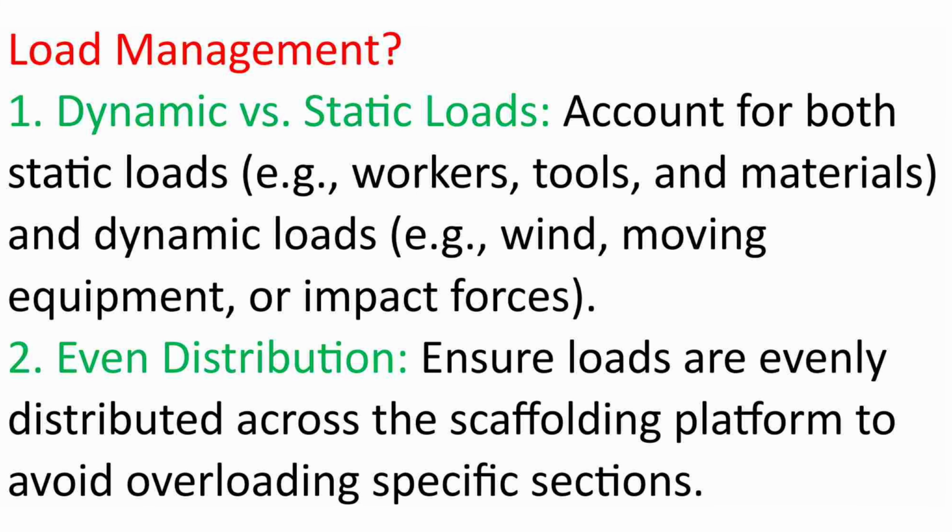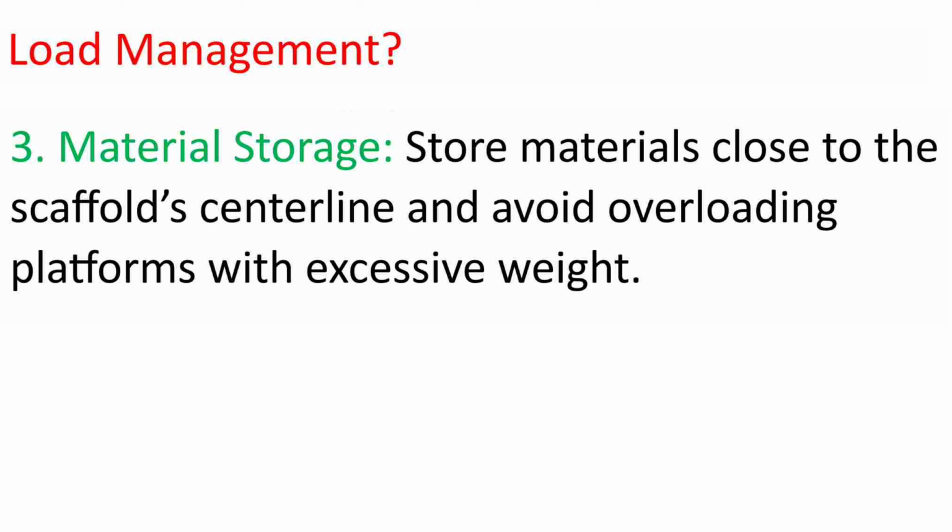Question: what are the load management? 1. Dynamic and static loads. Account for both. Static loads, for example, workers, tools, and materials, and dynamic loads, for example, wind, moving equipment, or impact forces. 2. Even distribution. Ensure loads are evenly distributed across the scaffolding platform to avoid overloading specific sections. 3. Material storage. Store materials close to the scaffold's center line and avoid overloading platforms with excessive weight.